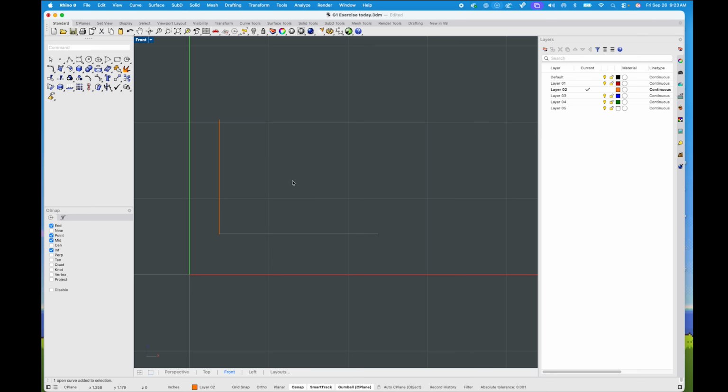And I'll show you what it looks like in 3D. But one thing I could do is just mirror it. So I can type in mirror. I can select the midpoint. I can basically tell it where I want the mirror to be. Gosh, I wish I had this on a drafting table, by the way. Ortho. To turn off the ortho, it's right here at the bottom. You'll see that there's an ortho button. Yeah, I see it. You can also hit Command F8. That's F8. It's a button. Function 8.